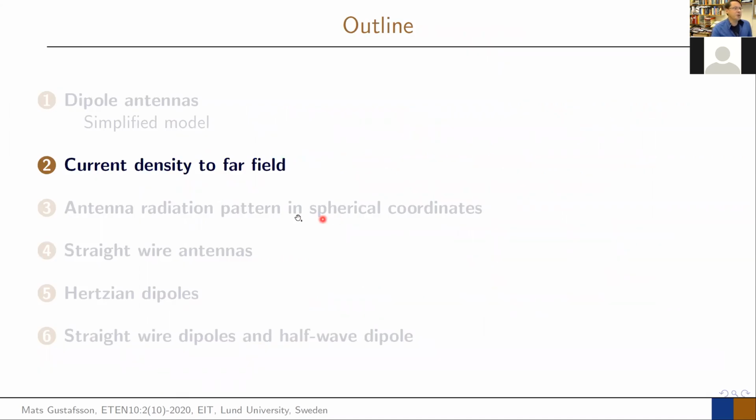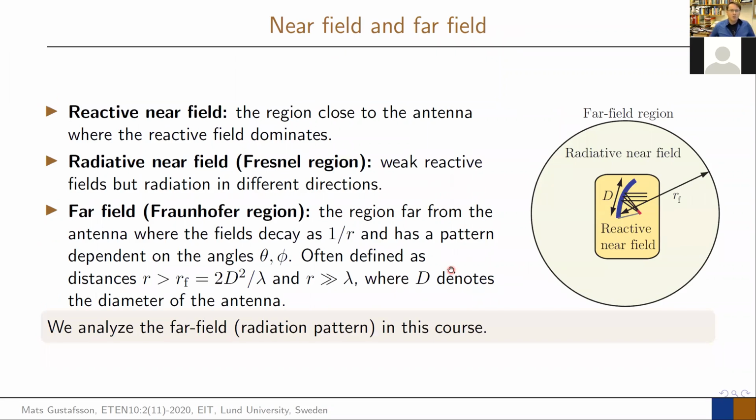So that means that we will look at this current, and now I talk about the far field, so I will define what the far field is. So what is the far field? That is that the radiation from an antenna can in general be very complex. So if we have an antenna here, so this is the picture of an antenna, in this case a very big antenna, here is a parabolic reflector, then I can be at different distances from my antenna.